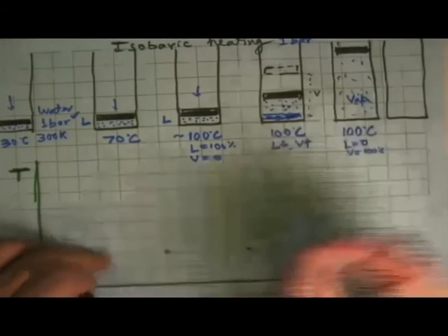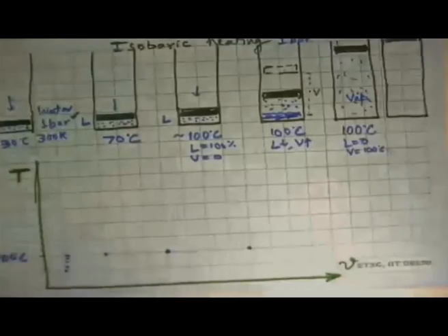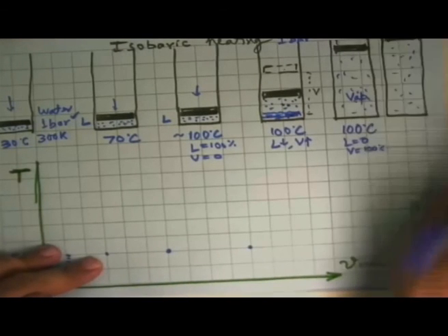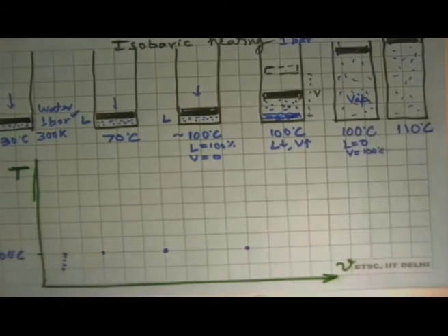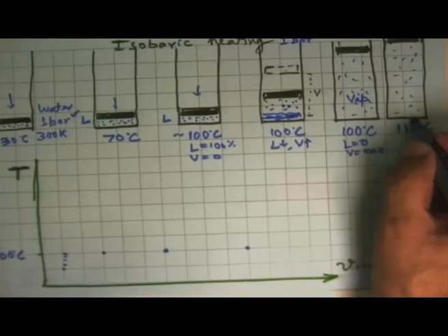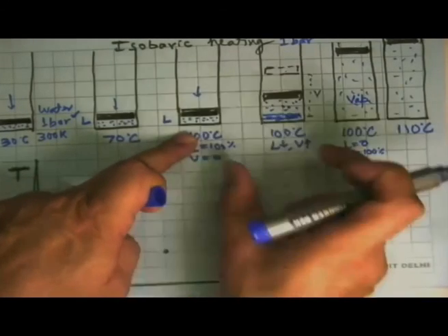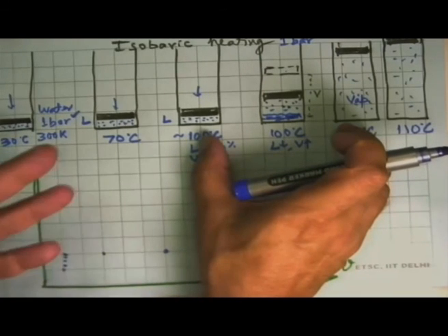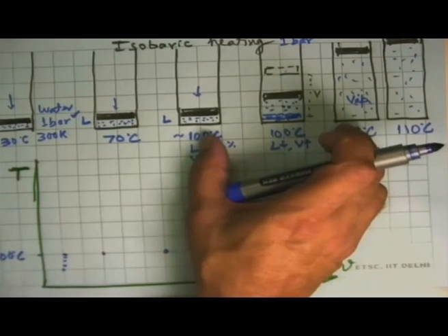We further heat it, the piston goes up, the vapor occupies all this, but now temperature has become say 110 degrees Celsius. So now from this point to this point, adding of heat started increasing the temperature of the system. Up to this point, heating was increasing the temperature, but in this region, heating of the substance was not changing its temperature but changing its phase.